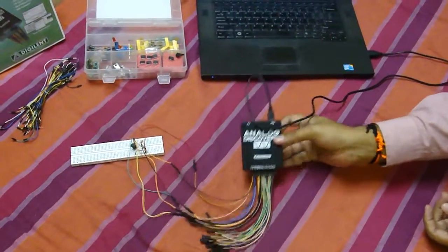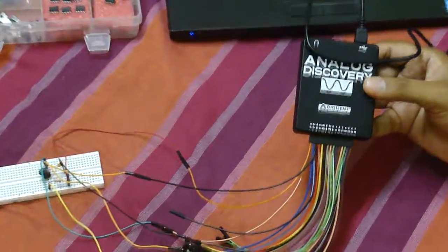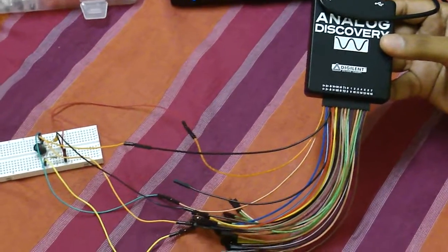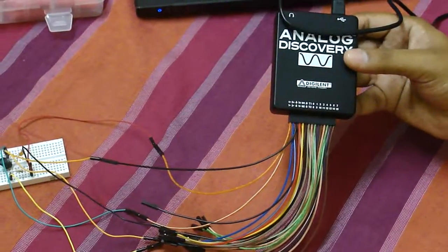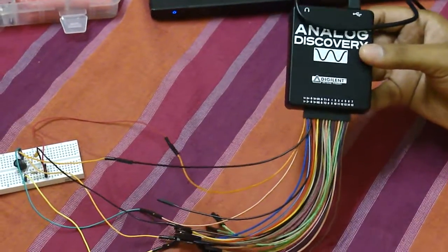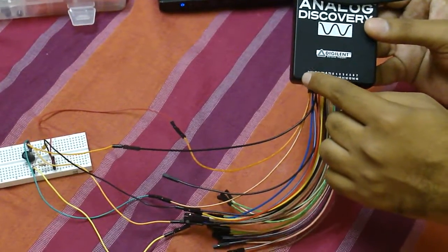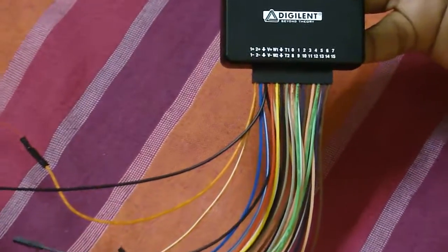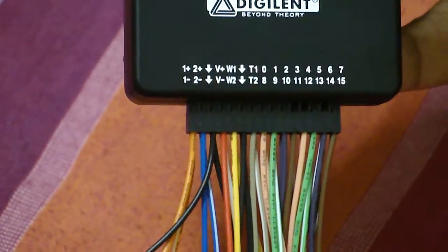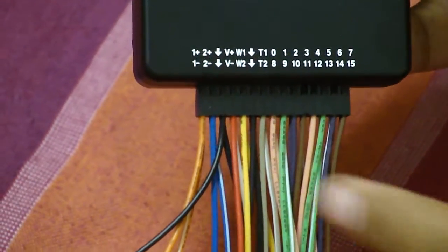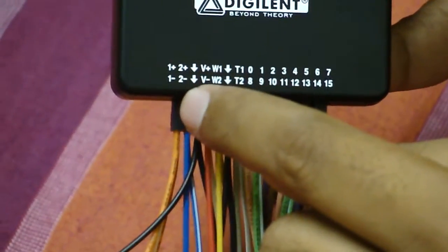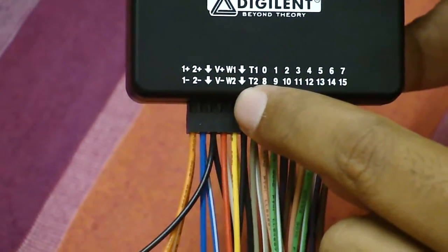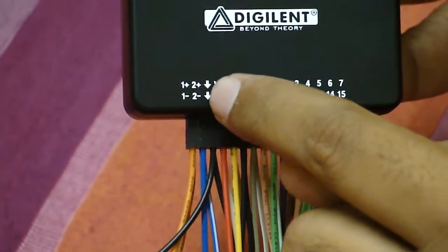Analog Discovery Kit, as you are seeing over here, is a very portable, compact platform which gives you a powerful range of features such as a dual channel oscilloscope, which you can see over here. +1 and +2 and -1 and -2 formulate the positive and negative terminals of the dual channel oscilloscope. And apart from that, you will get to see the 4 ground terminals which are offered in the Analog Discovery Kit, and plus it also gives you power supply